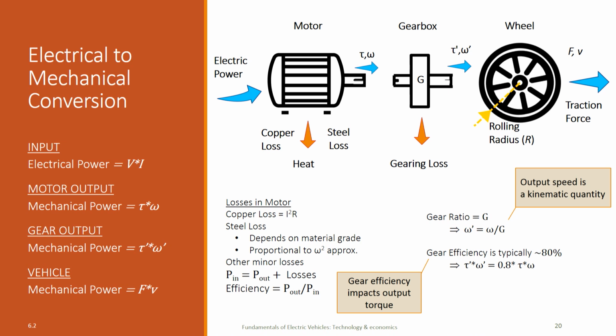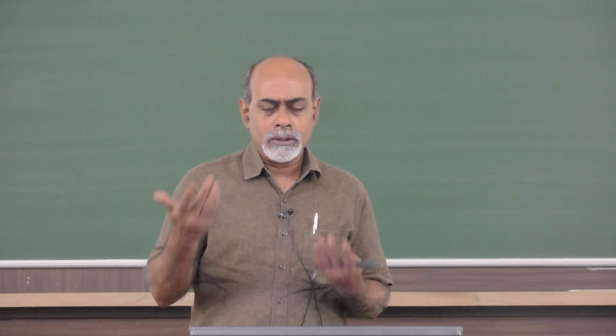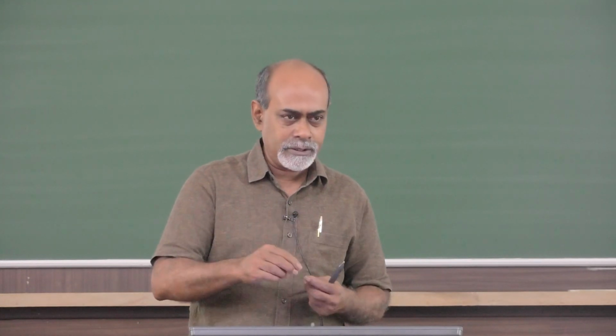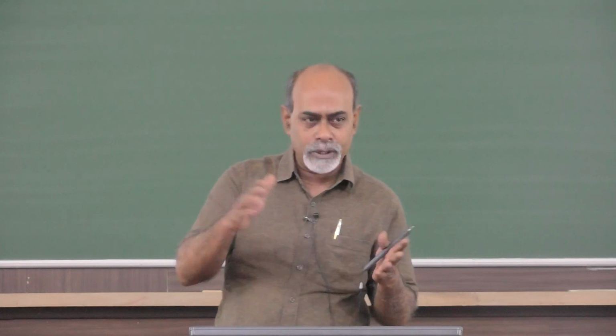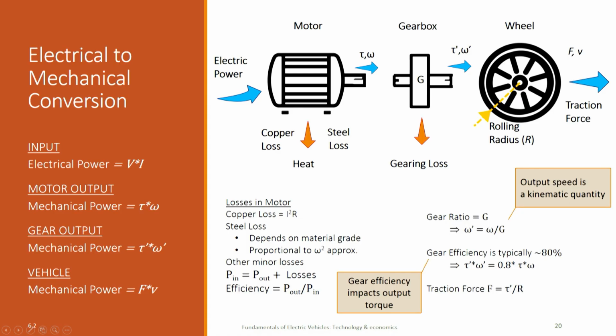Where does this loss go? Does it get converted to heat? Yes, the gearbox will get hotter. There is not a very strict rule. Some rule that many people use is that every pair of meshing gears is 5%, and normally this will be a 2-stage gearbox, that will be like 5 plus 5, 10%. But if there are any misalignments and other things or wear and tear, then it could be worse.